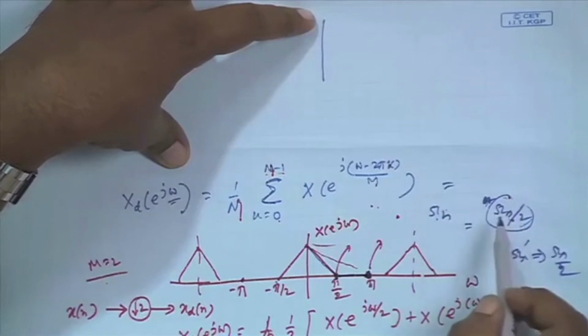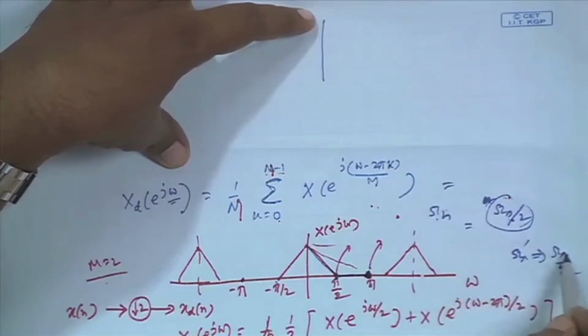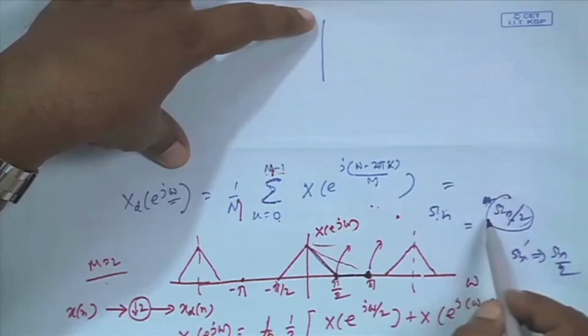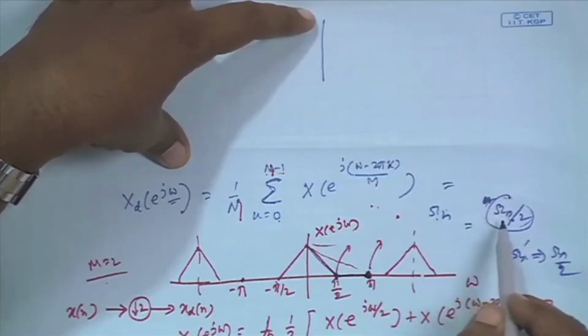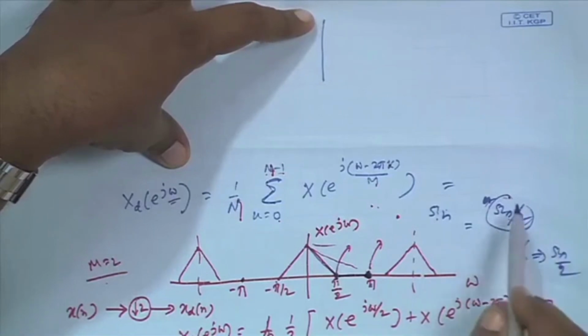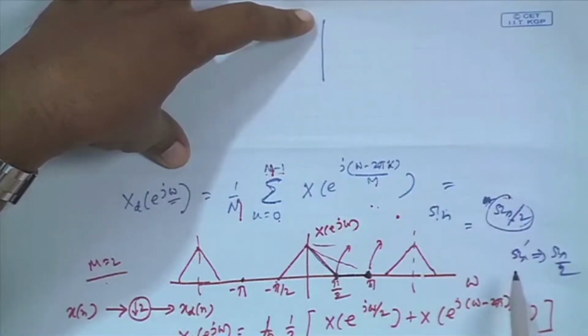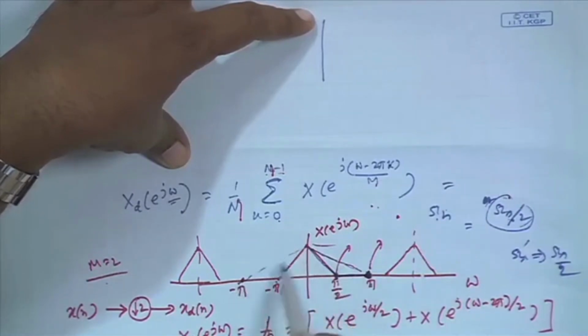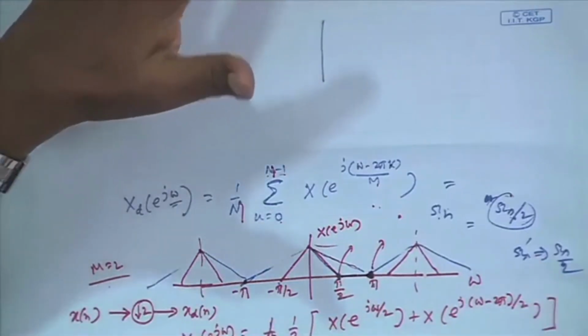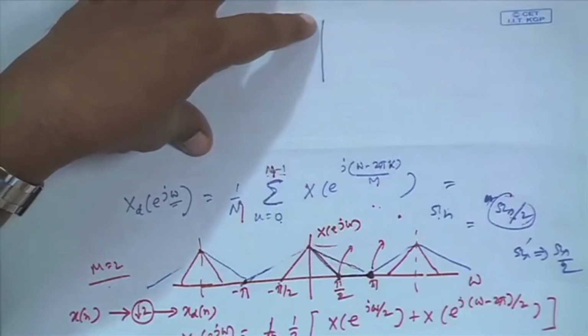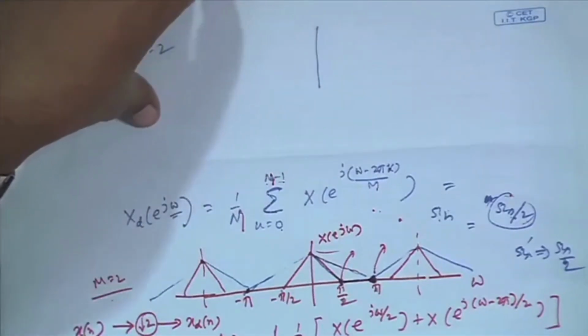But this is unnecessarily twice, I can bring it down. Instead of omega s I make it omega s prime, which is omega s by 2. So, half sampling frequency is half of this, that means it is equal to omega h now, because omega h was half of the original half sampling frequency. Now, half sampling frequency has been brought down by 2. So, the new half sampling frequency omega s prime by 2 will be same as omega h, but omega s prime by 2 always maps to pi. Therefore, omega h will map to pi. So, this would be like this then. No aliasing, this is what we should have, and we will see that by this formula also we will get the same figure, that is what we will see.